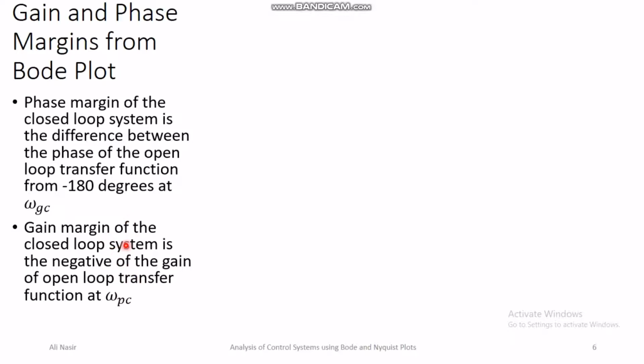If the gain at the phase crossover frequency is still positive, then the closed loop system will be unstable and there is no purpose in trying to determine the gain margin, because gain and phase margins by definition are the tolerance values against disturbances without losing the stability.